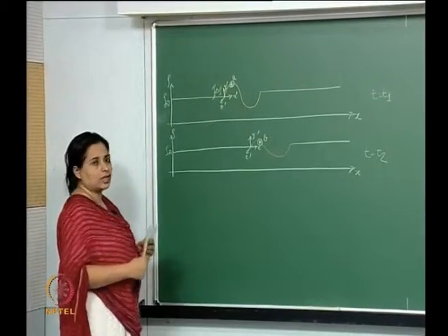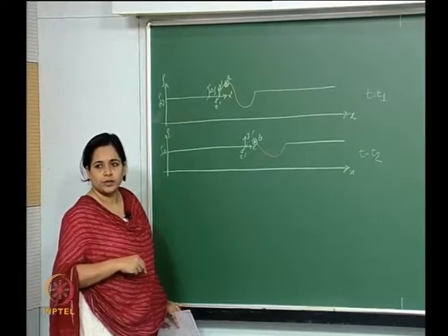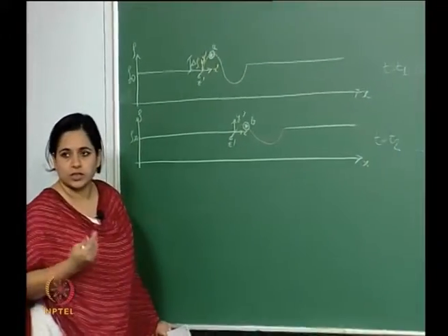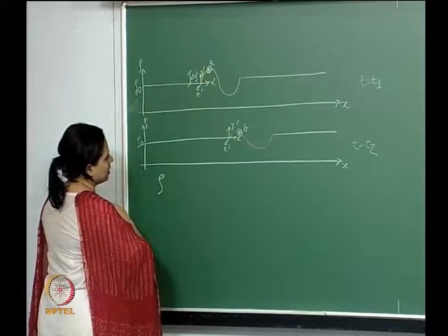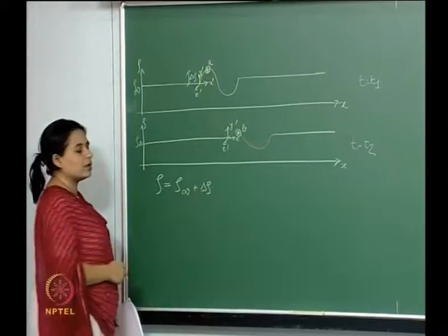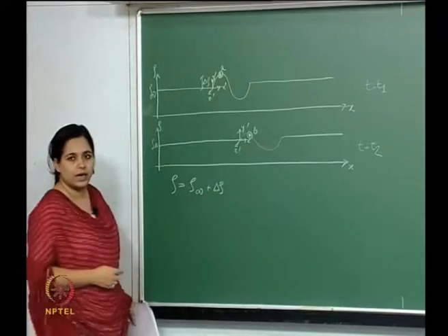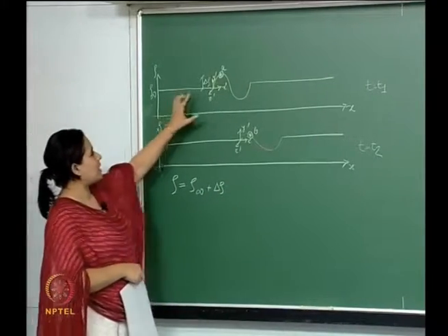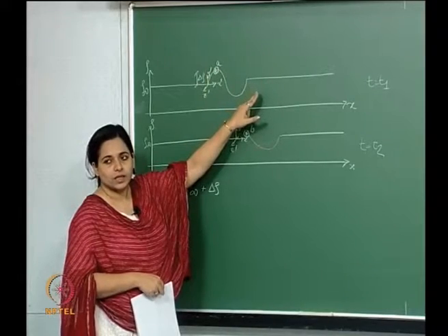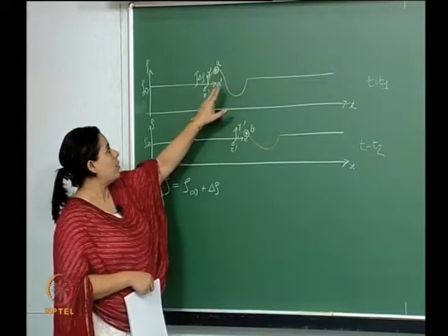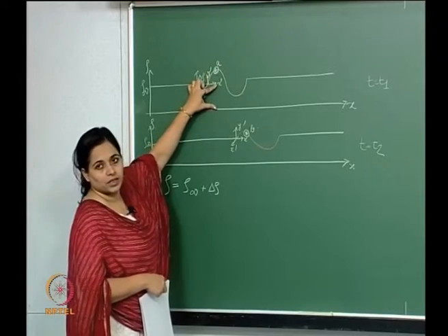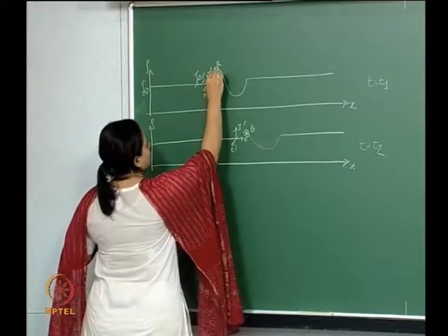Now, mathematically, we said the governing equations are the continuity, conservation of momentum and the energy equation. If I introduce the perturbations into that, the total density is actually the ambient density plus an induced perturbation. The local density and velocity here are due to this perturbation, but the total is when you add this local value to the ambient conditions, isn't it?